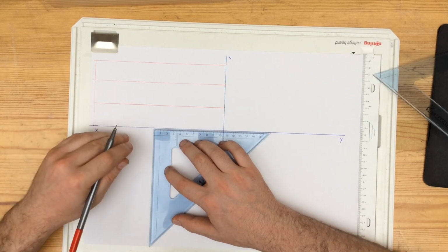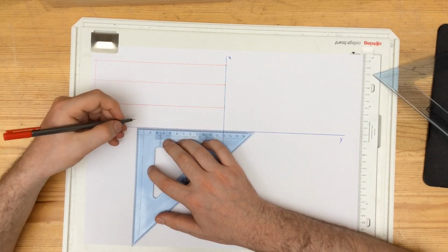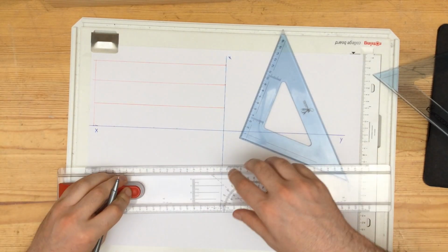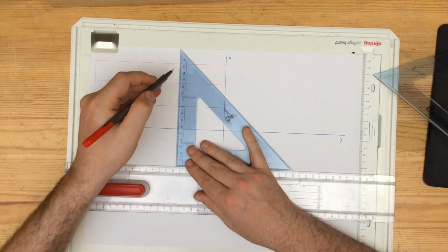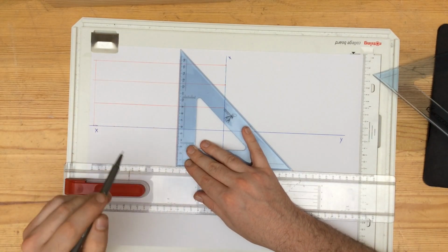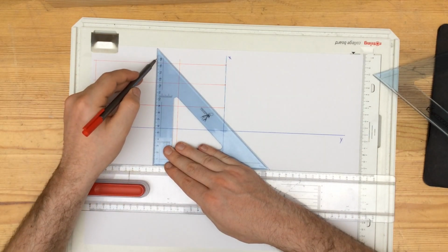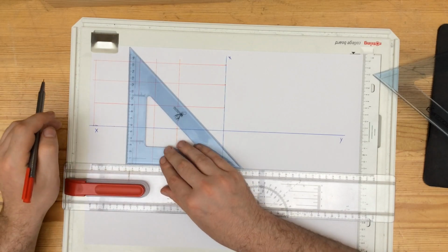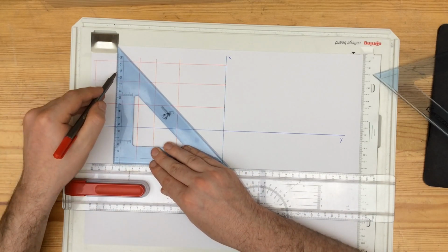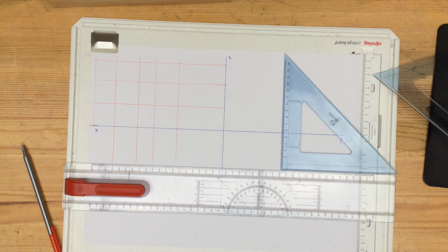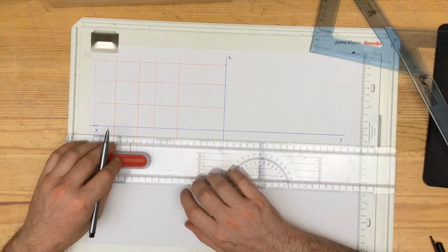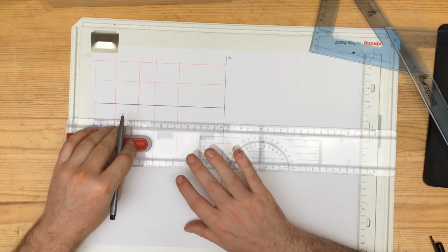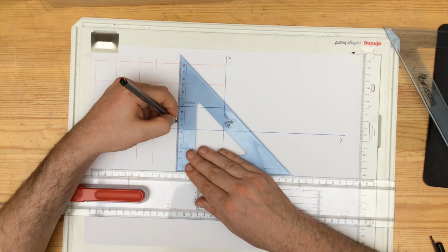I have also divided up any other horizontal lines that will be needed in the elevation. I now will mark any widths that I will also need in the elevation and draw them vertically straight up. With my black coloured pen, I am now going to darken in the full lines that will appear in the elevation for this particular question.